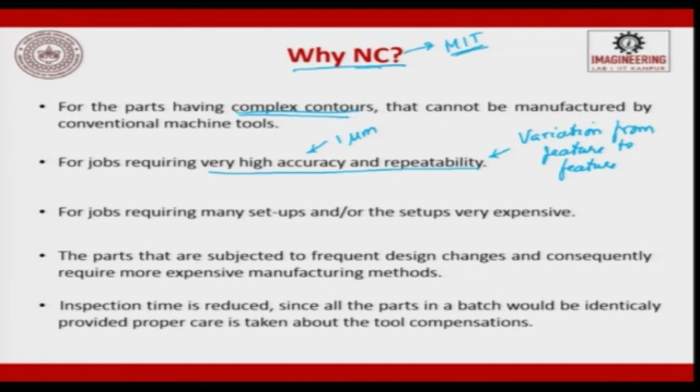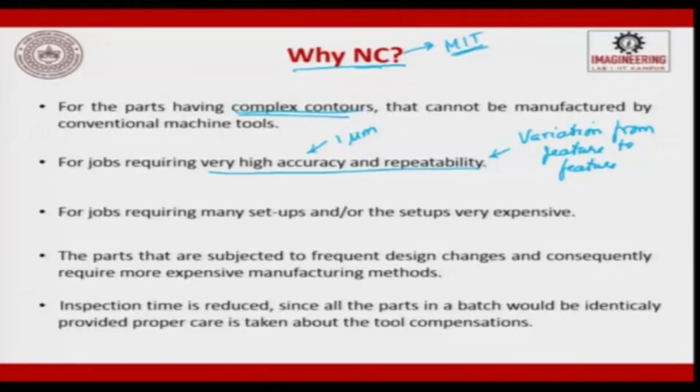For jobs requiring many setups or where the setups are very expensive. If there are multiple setups, what we do is we will have multiple tools. For example, drilling, turning, boring and then threading. All these things can be done integrated, putting several tools around a turret and having the workpiece in a spindle and doing the consecutive operations one after another in a single setting. This leads to very high accuracy in terms of referencing.